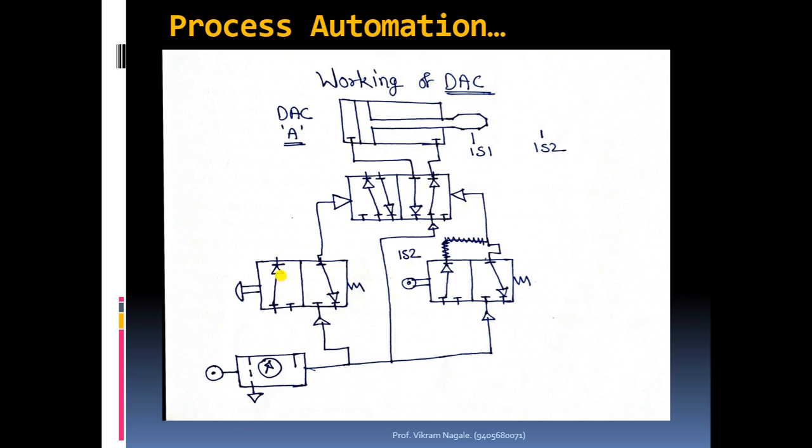Okay, that will shift, and whenever it happens, the supply given to the 3x2 valve with push button will be transferred, because here the block has shifted. So whenever this block comes in contact with the outer ports, then the air coming to this input port will go to the output side, that is port number 2, and that will be transferred to the left side of the valve. And whenever this side is getting pressurized, initially we will consider that there is no pressure or there is no valve on the right hand side.